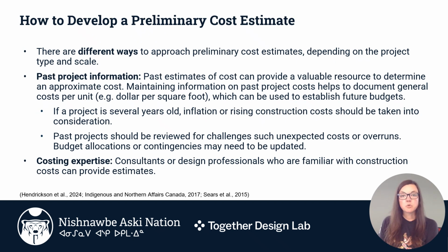How to develop a preliminary cost estimate. There are different ways to approach preliminary cost estimates depending on the project type and scale. Past project information can provide a valuable resource to determine an approximate cost. Maintaining information on past project costs helps to document general cost per unit, which can be used to establish future budgets.